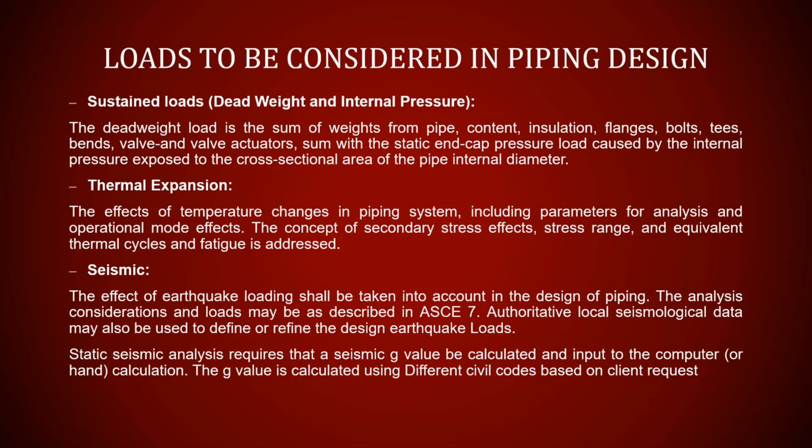The dead weight load is the sum of the weight from pipe containing insulation, flanges, bolts, tees, bends, valves, and valve actuator. Add to it the static end cap pressure load caused by internal pressure exposed to the cross-section area of the piping internal diameter.